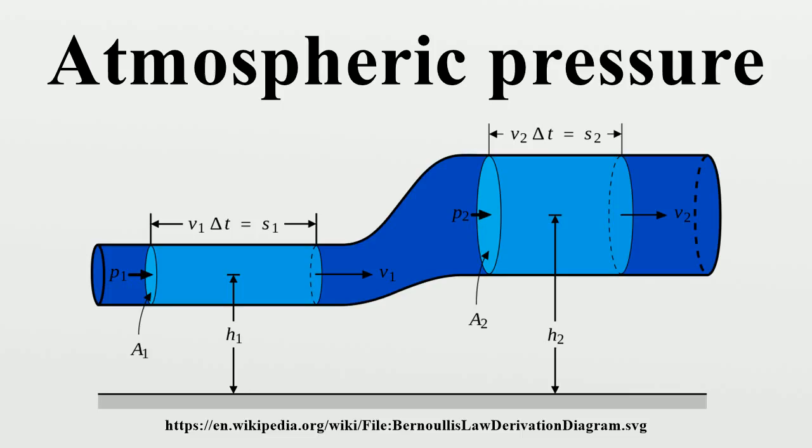QFE is the barometric altimeter setting that causes an altimeter to read 0 when at the reference datum of a particular airfield. In isotemperature conditions, the altimeter will read height above the airfield's runway threshold in the vicinity of the airfield. QFE and QNH are arbitrary Q codes rather than abbreviations, but the mnemonics, nautical height, and field elevation, are often used by pilots to distinguish them.